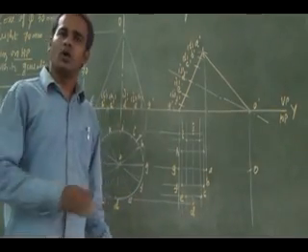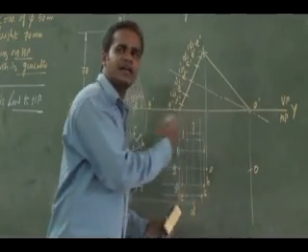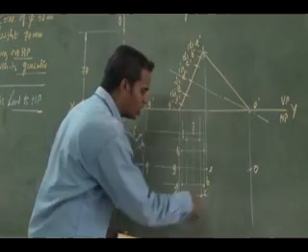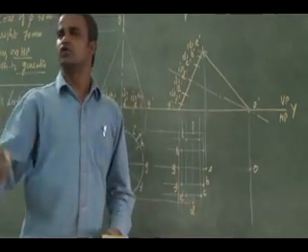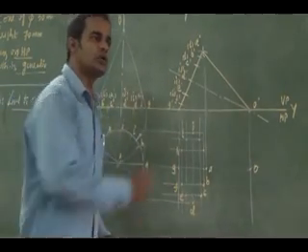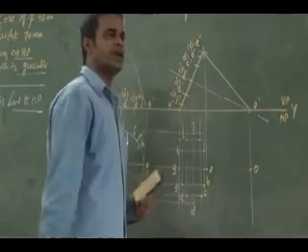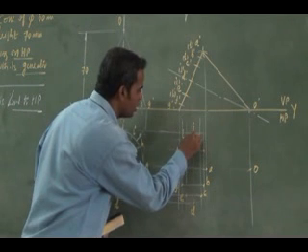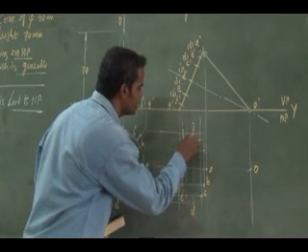So what is that visible line? Is it a circle or is it an ellipse? It will be something like an ellipse. So I have to connect all my base points as a curve. First of all, use your 2H pencil to get a smooth curve. Then finally you darken it. You see here, first you try to get a smooth curve using your 2H pencil.